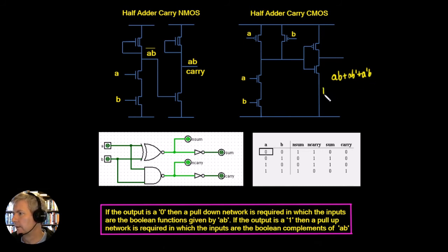So we could have a B, and then you would have A for this one, plus not A, and then we'd be left with the centre one, which is going to be A B not. A plus A not is just a value of 1, so that would be B plus A B not.